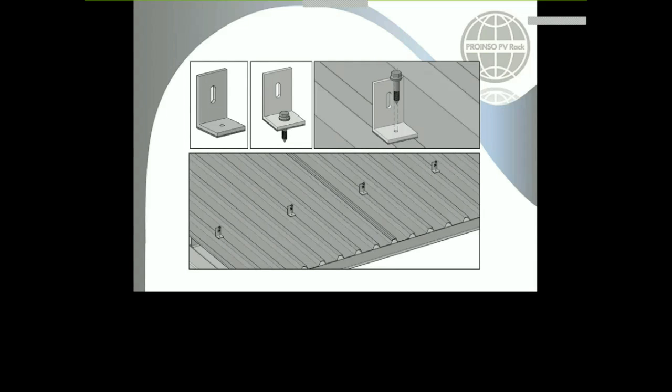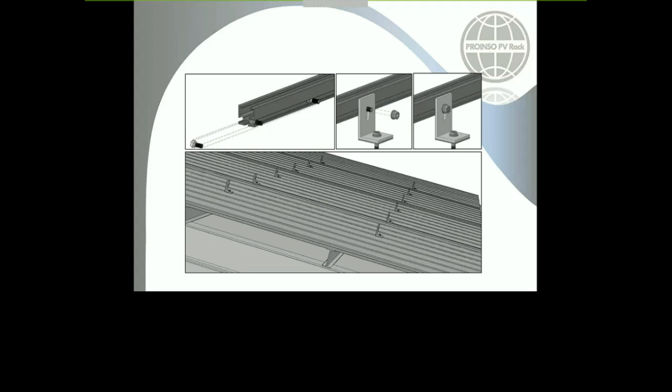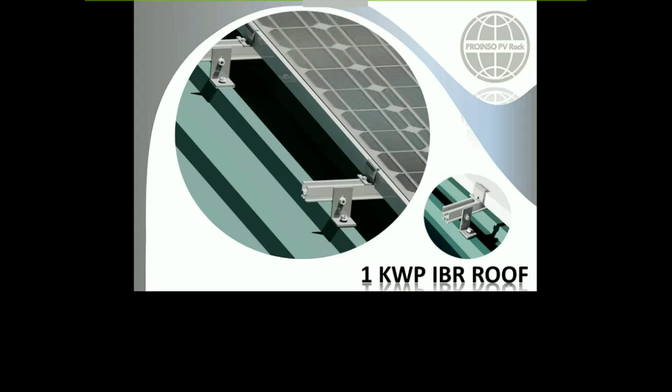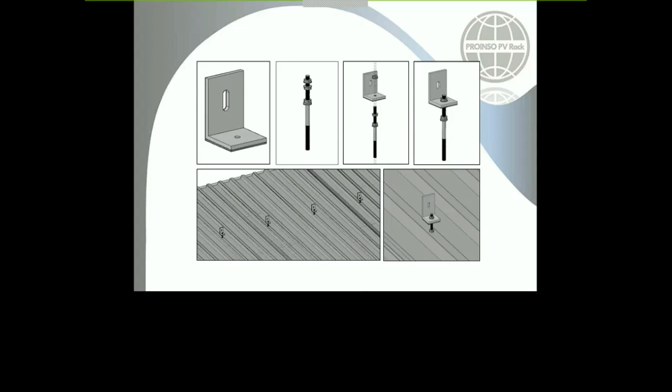If I may add to that, Clinton, in those specific circumstances, you run the risk of creating issues with your panels, with delamination, etc. So a suggestion would be to maybe look at the hanger bolt solution, whereby you can raise the L bracket off of the corrugation and mount your panels elevated off your roof, and then allow enough air movement under the panels to allow for cooling of the back sheet, etc.